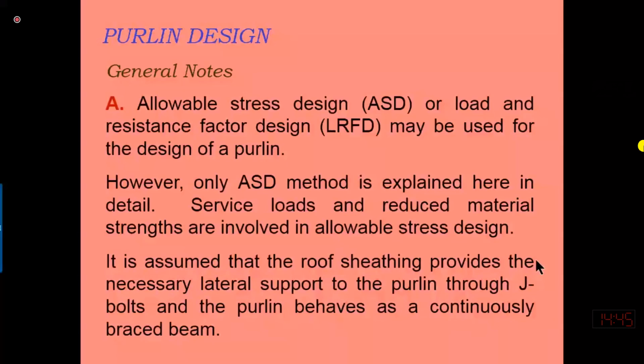Actually, for the purlin design, we can use either the ASD method or LRFD. But for convenience, in this design class we will study the ASD method only. Service load and reduced material strength are involved in allowable stress design.